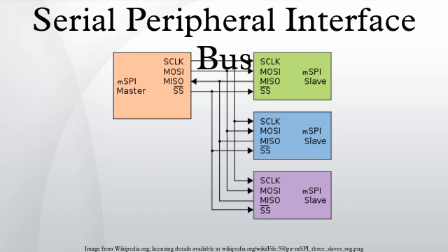SPI does not support hot plugging. Interrupts must either be implemented with out-of-band signals or be faked by using periodic polling, similarly to USB 1.1 and 2.0. Some variants like multi-IO SPI and 3-wire serial buses defined below are half-duplex.